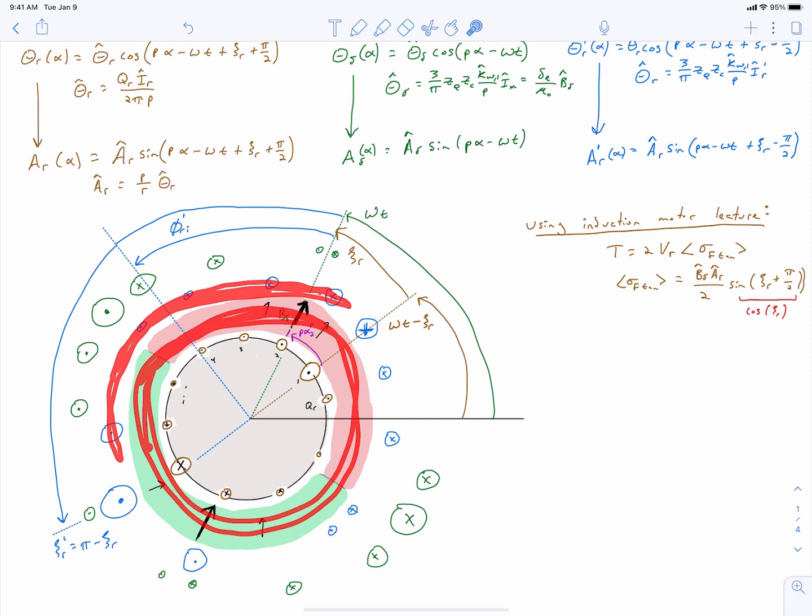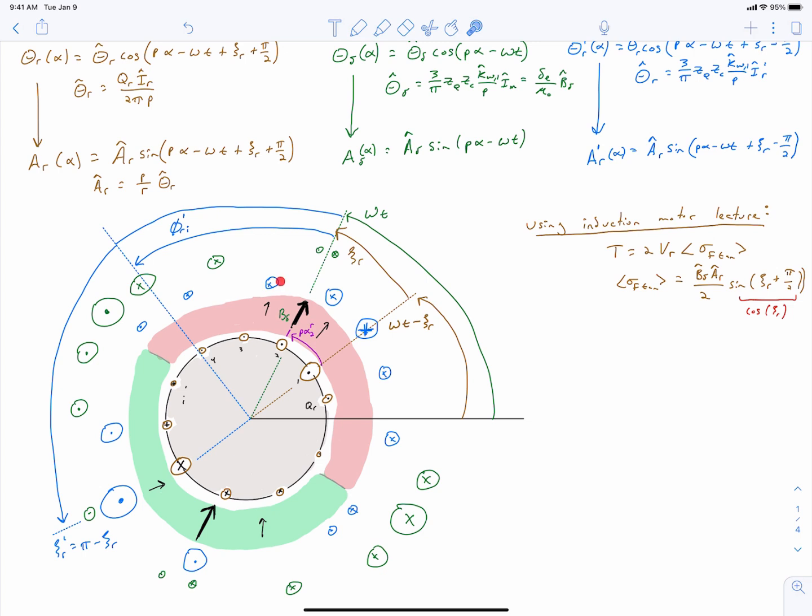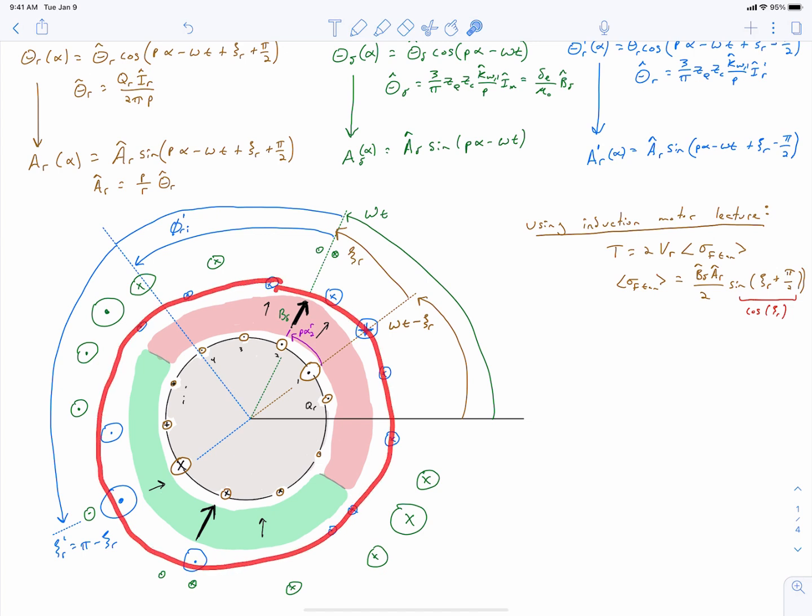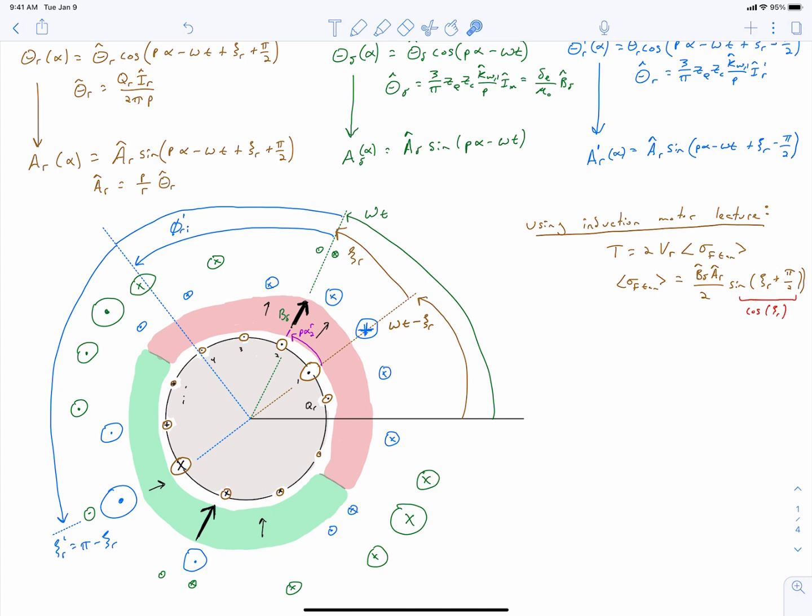In the AC machine design sizing unit, we had a magnetizing field created by the rotor, and then we just looked at the stator's linear current density. In this case, we're looking at the stator's linear current density, but only the portion associated with reacting to the rotor fields. We're leaving alone the current density associated with creating the magnetizing fields, because we established in that previous video that any current that's aligned with our magnets will create no torque.